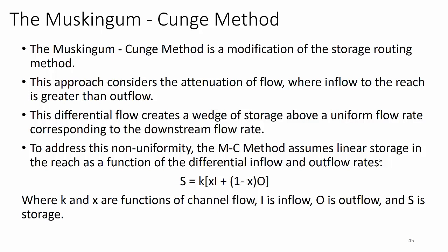So S, the storage, equals K times [XI plus (1 minus X)O], where K and X are functions of channel flow, I is inflow, O is outflow, and S is storage. Conceptually, it's just a linear regression equation.